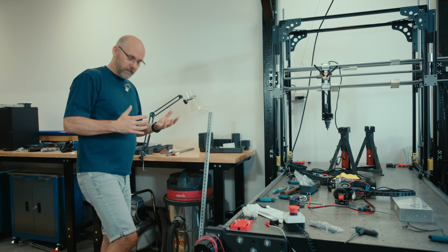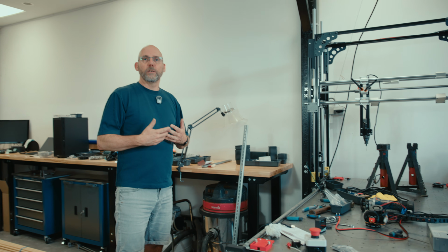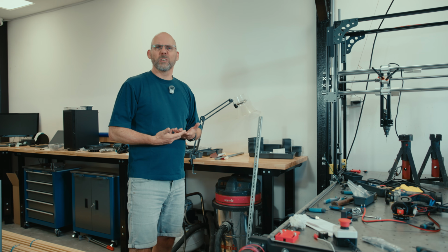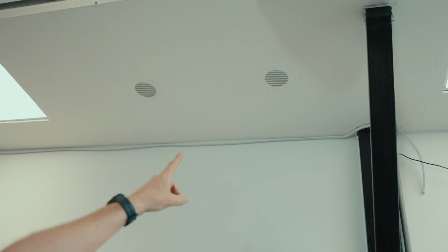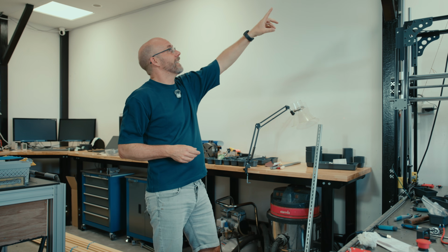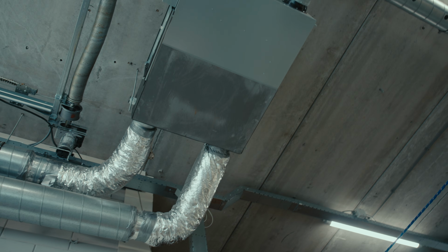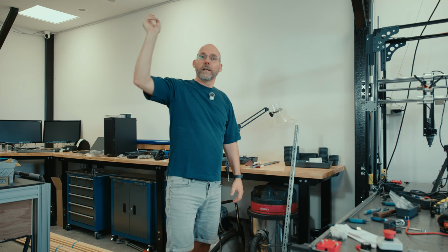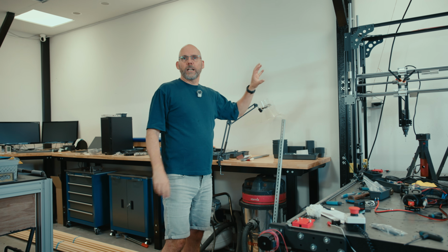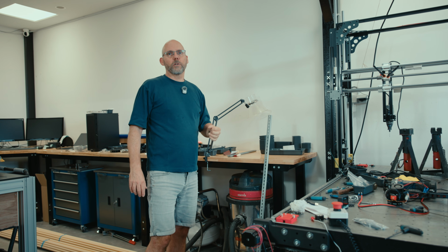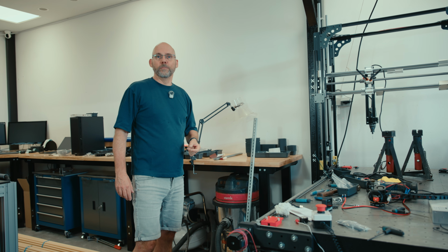The other aspect of it, and that's a little harder I think for the camera, it will create fumes, especially when we go to laser. Obviously the fumes are pretty nasty, you don't want those in your work environment. But if you look here, there's ventilation shafts here that go to a central cleaning system, air filtration system that goes outside. So we will also be hooking up this whole setup to that ventilation system and obviously running the ventilation system when we run the CNC mill.